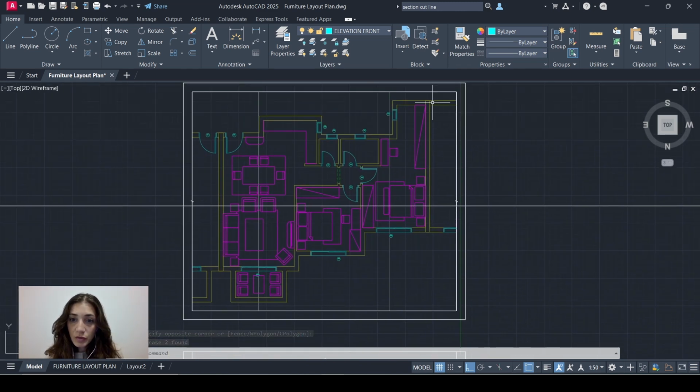So even though these walls, this one right here and this one right here, define the limits of the apartment, the plan is extended to show a part of the neighbor's apartment on the right side and the left side. So to project an accurate elevation, I need to show this part of the window that's here, and the same applies to this part of the door window.